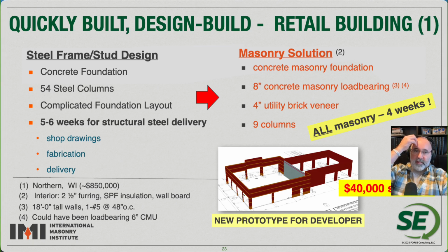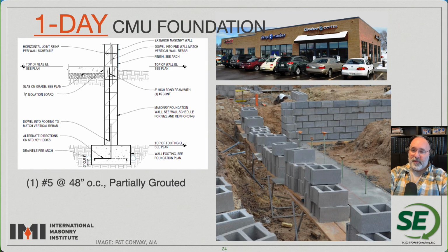Having the load-bearing concrete masonry building was certainly very important in the design, and that also had a one-day masonry foundation. Now, it wasn't an overly huge structure, but we didn't have to set forms and set reinforcement and pour concrete and wait a couple days and strip forms. We just set the block, reinforced and grouted, and we were done, the entire foundation for the building in one day. So it was a very simple step, and we certainly saved a lot of time and money on the project.